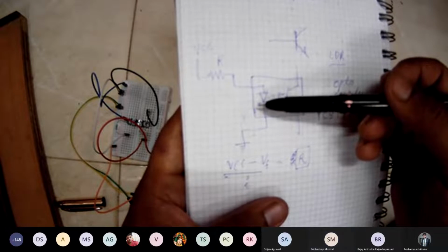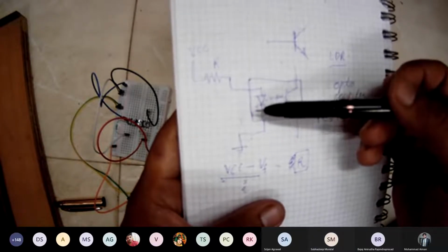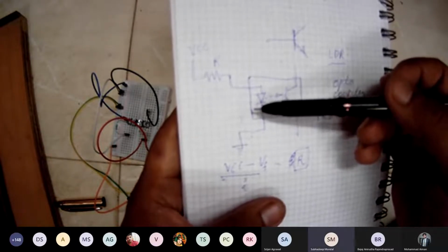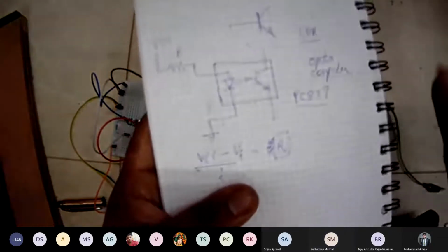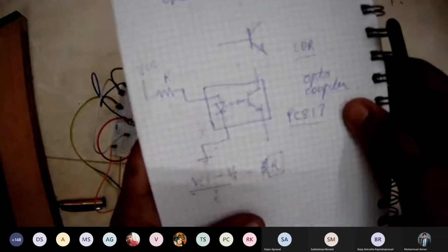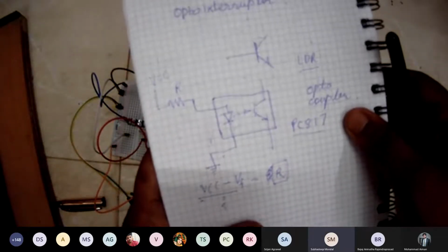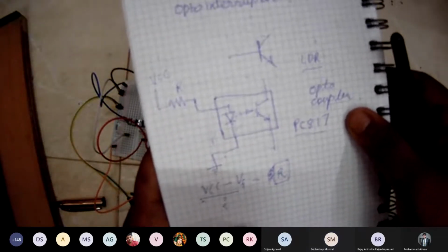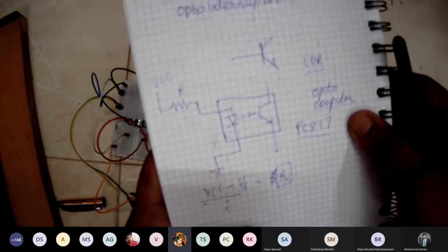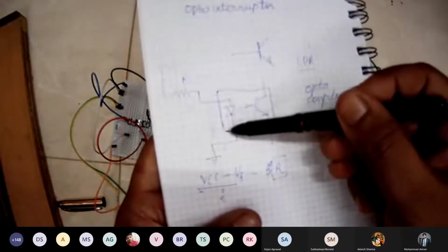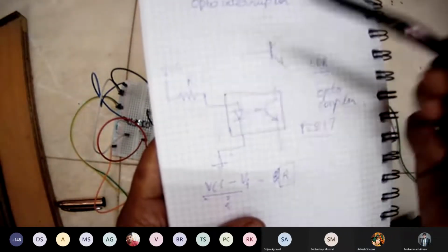And sir, here the 0.7. Pardon me. I'm asking, is it a 0.7 volt drop there? Yeah, but it's not universal. The 0.7 volt drop is not universal. And here I is the current through the diode. Yes, it is the current through the diode, and consequently it is also the current through the resistor as well.